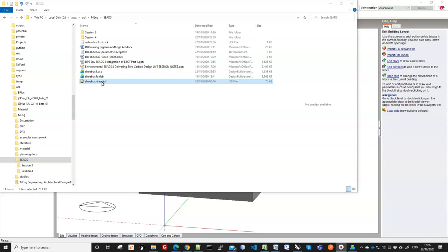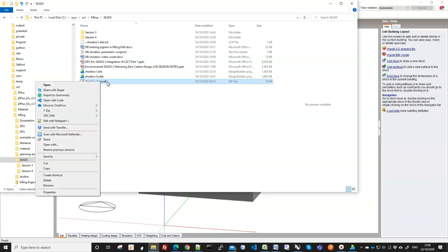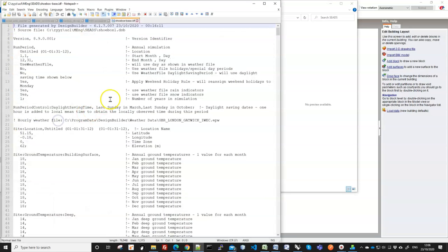So what's in this file? We know it is a text file, so let's open it in the text editor. There we go. You see the syntax of this file is fairly straightforward. The exclamation mark marks a comment line, like in this one and that, and also here. If all the comments are removed from this file, it won't affect the model.